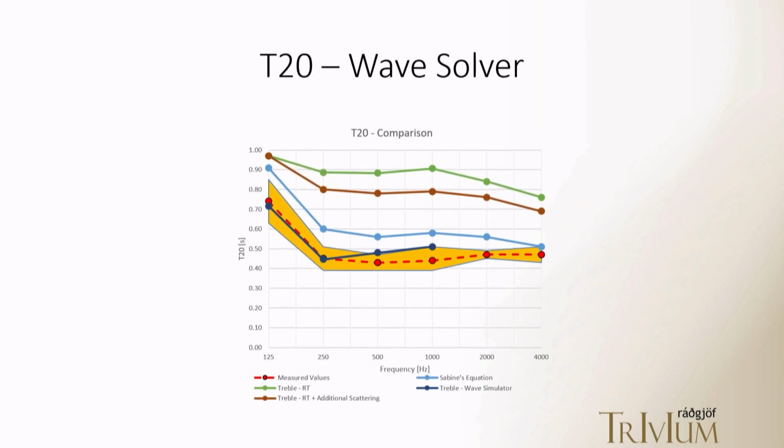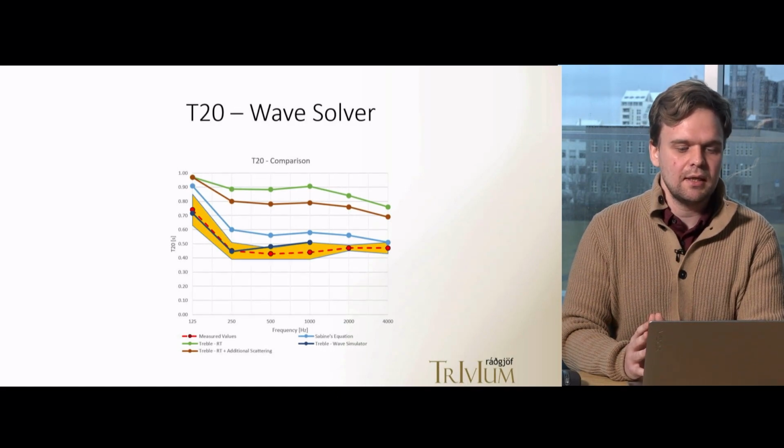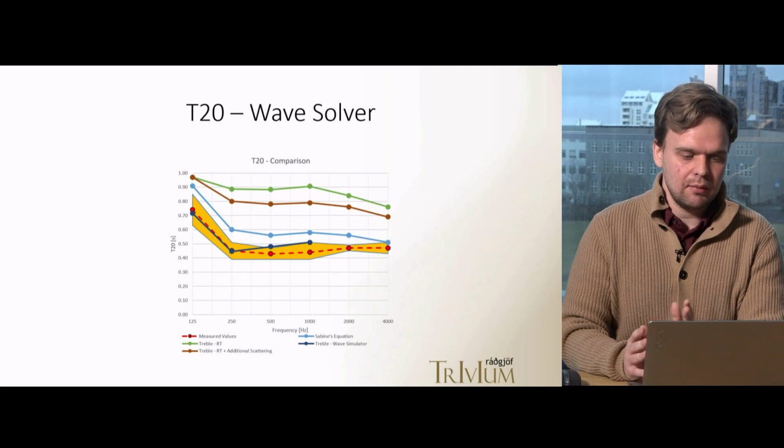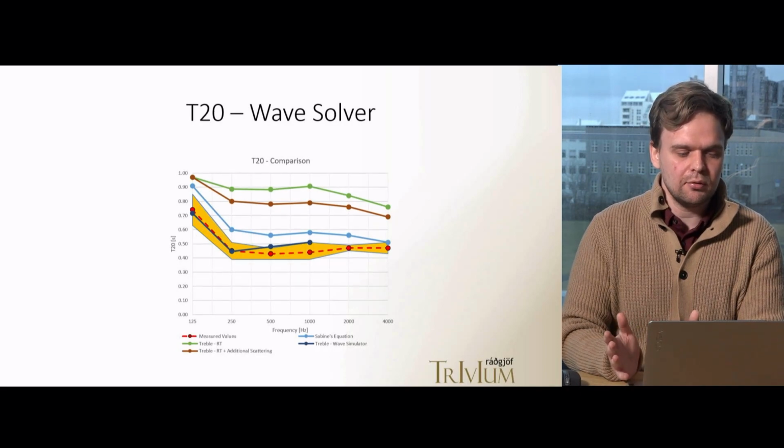And again, at 500 Hz and 1000 Hz, we are basically one standard deviation above the mean. But as I've already mentioned twice now, I am underestimating the absorption coefficients in these frequency bands or octave bands. And on the shelves, I'm doing that knowingly, so keep that in mind. I think these results are quite great, and being able to accurately predict the reverberation time at low frequencies like this in this tiny room was a complete revelation when I first started working in Treble.